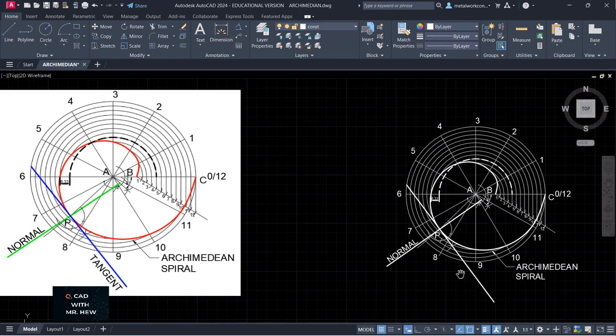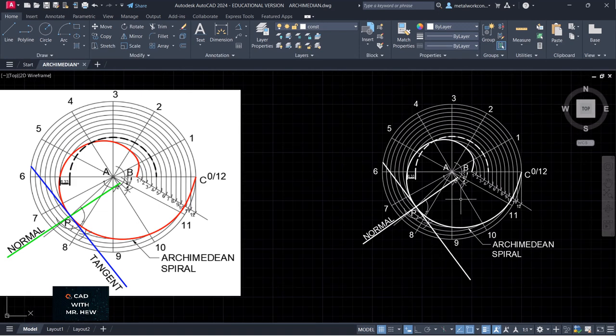We're going to label tangent right here, all right? So the angle here for this line, I believe will be the same, 335. So let's try. We're going to go single line text. The start would be here. The height, we're going to make it 6. Enter. What's the rotational angle? 315 degrees. Enter. Good. There it is.